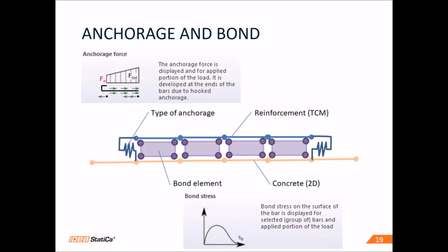A little bit about the tension core model, how it's connected to the concrete. We developed a bond model or the anchorage model, and this is just the model of how it works. The concrete is connected to the reinforcement by special finite elements with the springs in the end, and this enables us to give you results about the anchorage force, total force along the length, and also the bond stresses. I will speak also about it later.